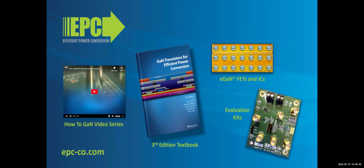The difference is this: if you do an inverter based on MOSFET, you do not have this possibility, because the problem is that MOSFETs cannot switch very, very fast. So either you go very, very slow, or if you want to switch a little bit faster, then you need to put a filter, but this filter needs to be very big. With a GaN FET, I'm talking about more than 1 meter cable. I'm talking about several meter cables.